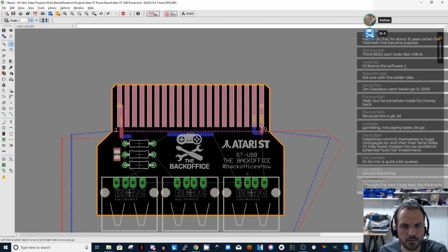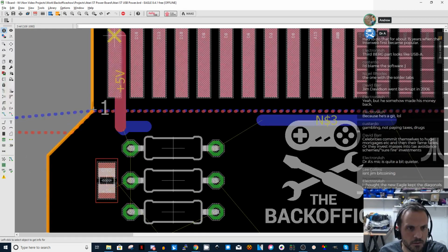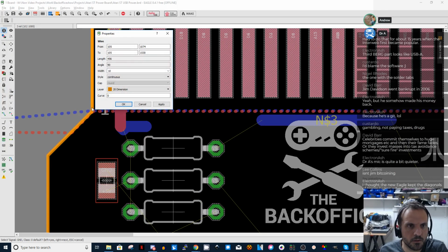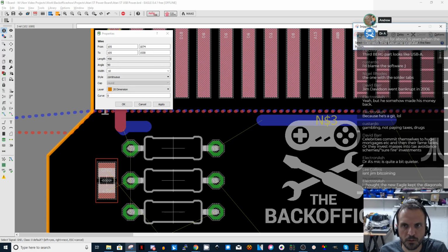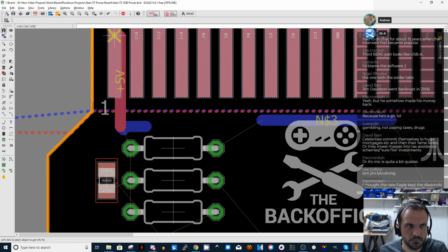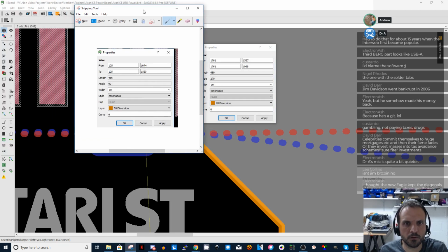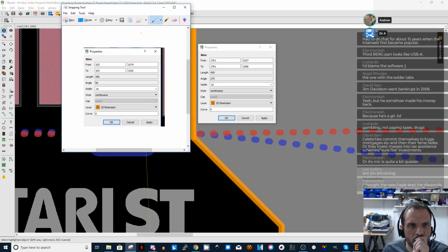So you've got the pump that sits outside, and the pump has 3 ports on it. It has one that sucks the water in for filtering and heating it, and pumps it back into the hot tub. That's the filtration. Then you have a third pipe on it that is your blower. So you turn it on, that pumps the air through. So you've got the pump, and then you've got the actual tub itself, which is the inflatable paddling bit. There is a rubber non-return flap that is molded into the port for the blower.